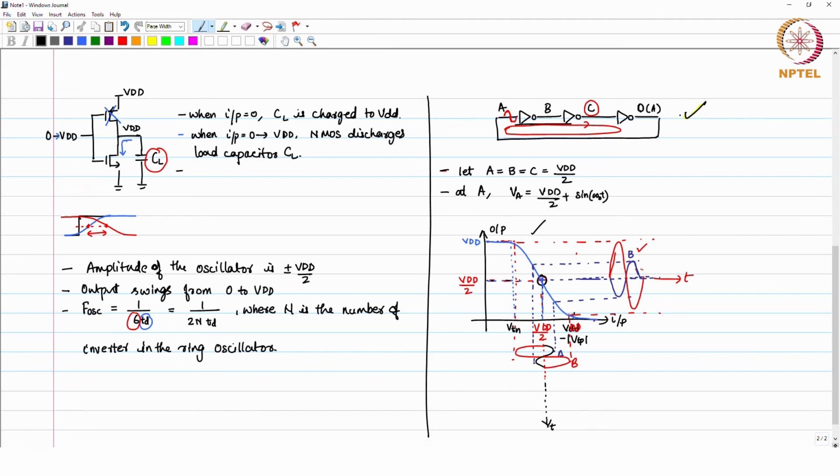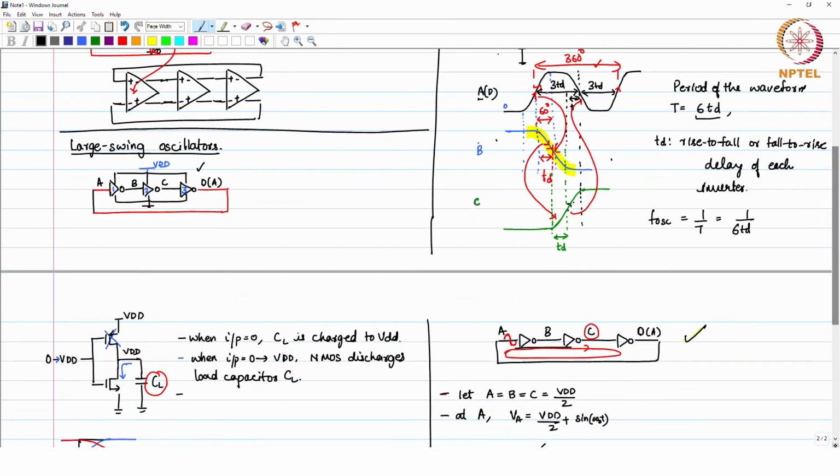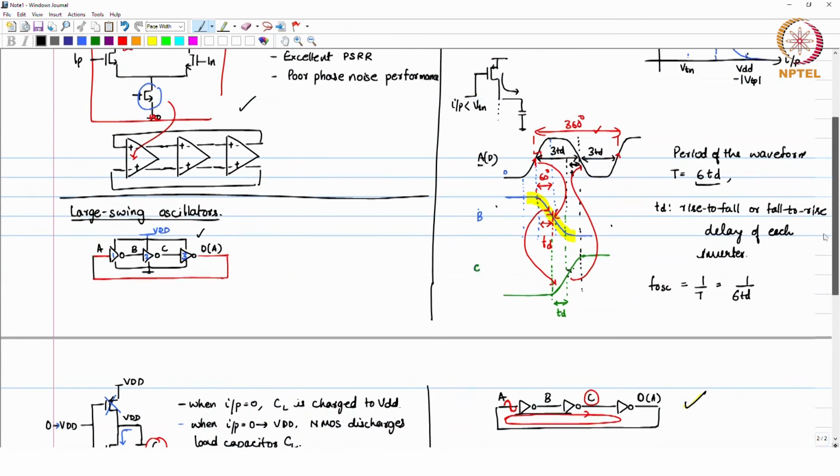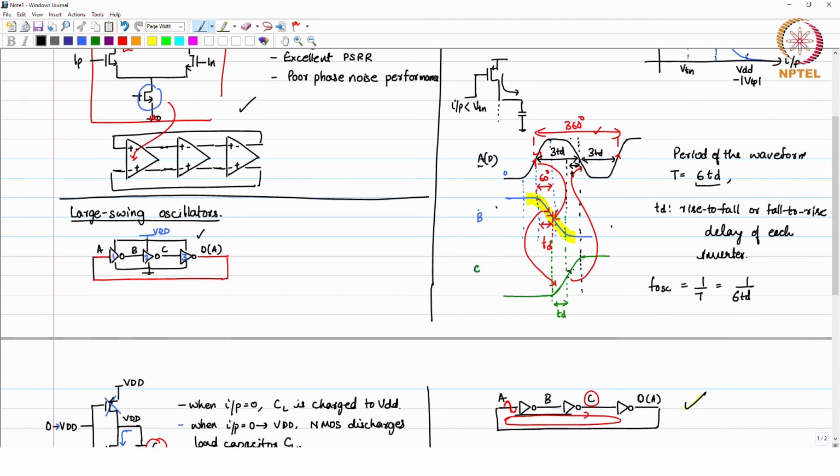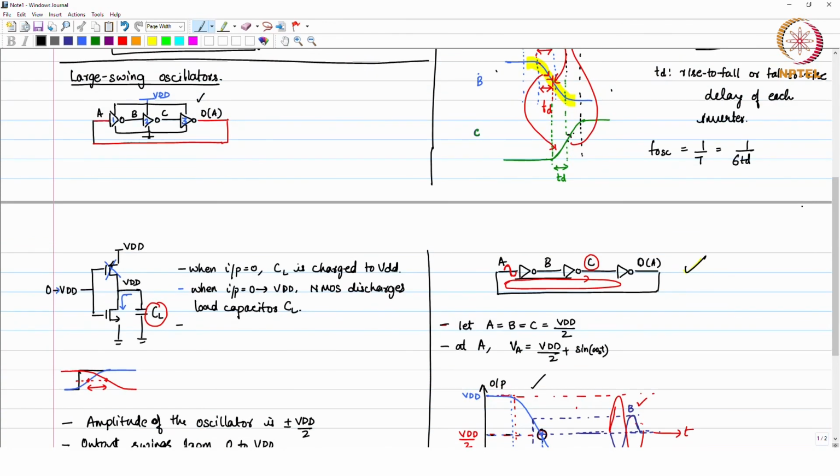But one important thing is that we cannot apply our loop gain or Barkhausen criterion for the square waves, because when the MOSFETs are off, the linear gain model does not prevail there. You can apply the linear gain model only when you have linear gain.